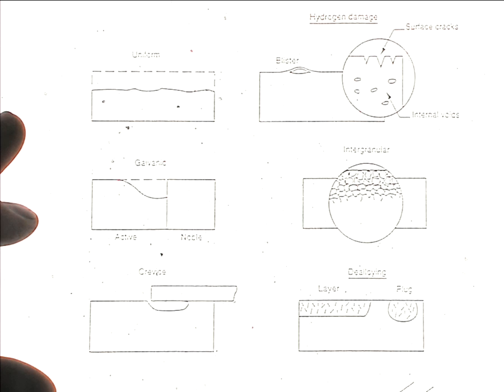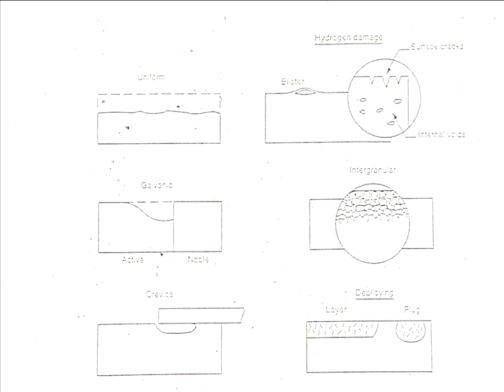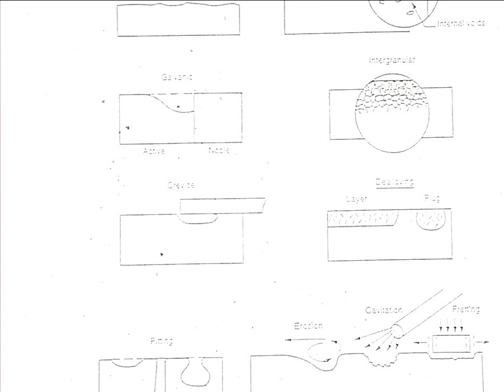If you remember, we were talking about modes of corrosion, and we'd gone through from uniform corrosion, where you get an even gradual loss of cross-section thickness, to looking at some forms of localized corrosion, where you get increased attack in some particular area of the component. In the case of galvanic corrosion, it's in the more active material closest to the cathode material.